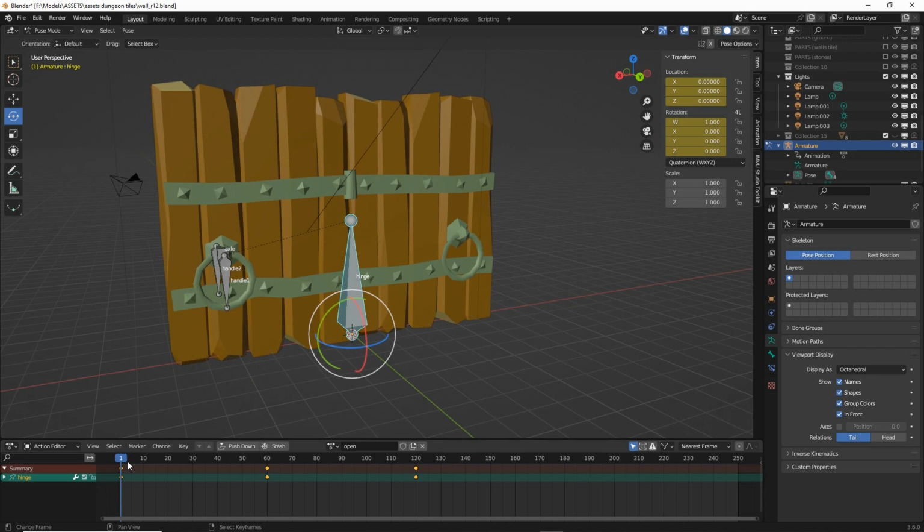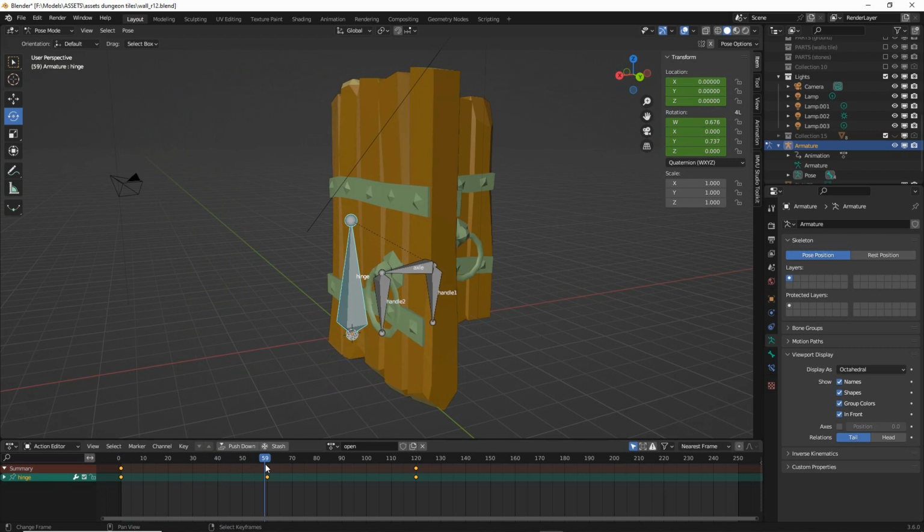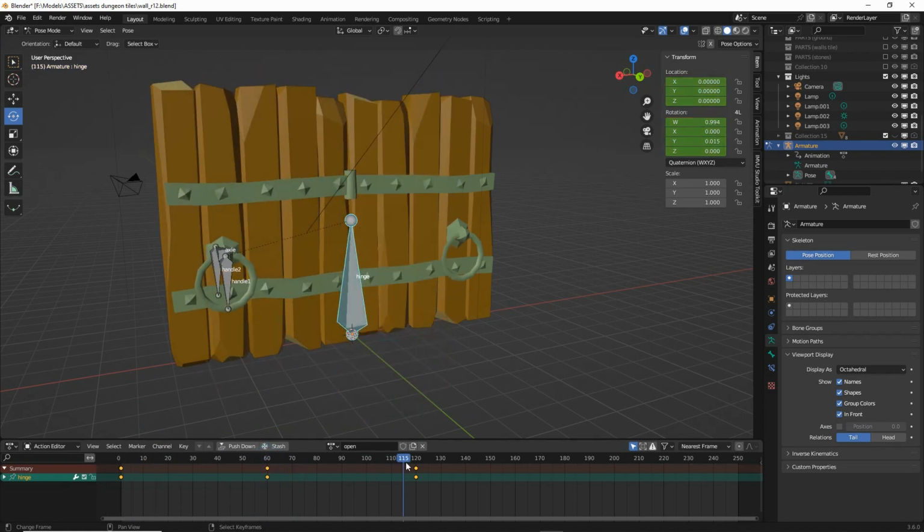So again, depending on where this is being used, we can either do it this way, where both the open and close is part of the same sequence. Then within the engine tech, the start and end frames are set, so it pulls in different actions from the same sequence, or you would have to create a new sequence. So if we had to create a new sequence, what we would do is click on the file icon. That duplicates this sequence, so let's call this one close.